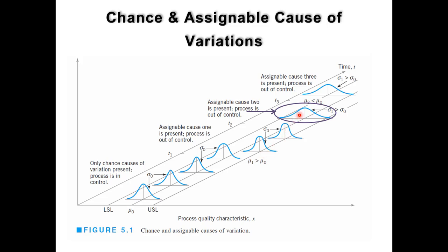But the following data set, on the seventh point in the time sequence, also has the occurrence of assignable causes. As such, you will see some points located below the lower specification limit, and some going beyond the upper specification limit.